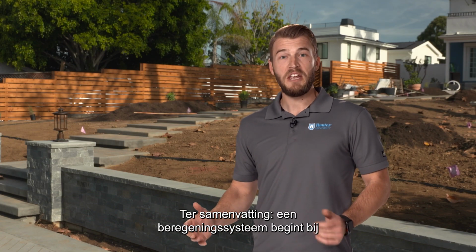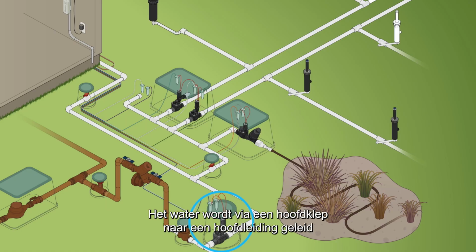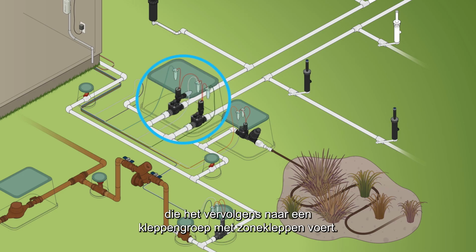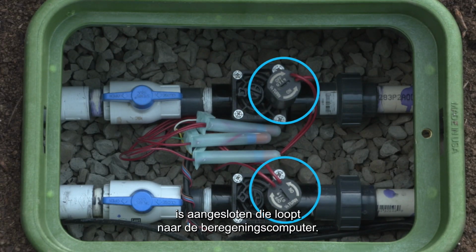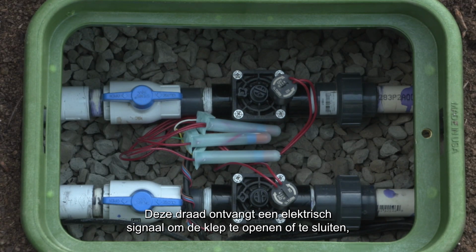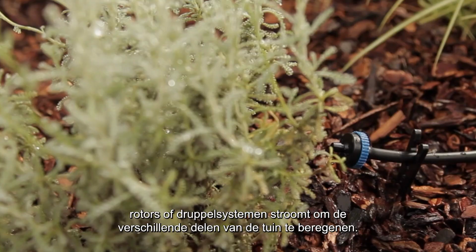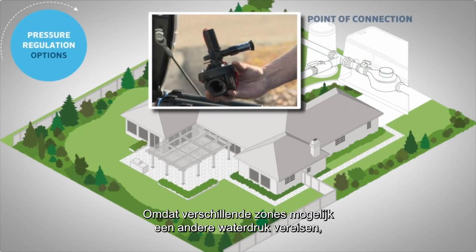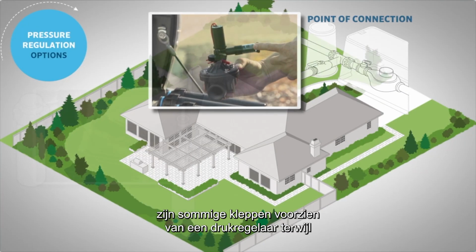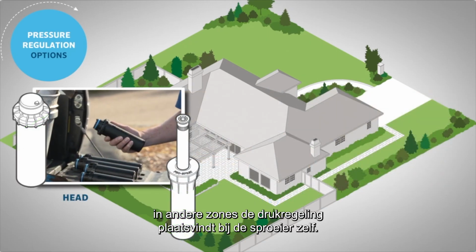To recap, an irrigation system begins at the point of connection from an incoming water source. The water is moved through a master valve to a main line that then makes its way to a valve manifold group of zone valves. Each zone valve has a solenoid on it with wire running from the controller that receives an electrical signal to open and close the valve, allowing water to reach its zone of sprays, rotors, or drip products that irrigate different parts of the landscape. Because different zones might need different water pressures, some valves are pressure regulated, while in other zones the pressure regulation may occur at the sprinkler body.